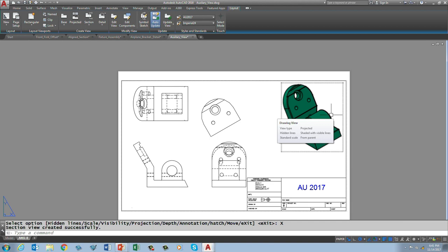Look at the drawing. What's wrong? There's something missing. What's missing? The label is missing. No, the label's missing. What else is missing? Something else is missing. The cutting plane line. Did you say cutting plane line? Very good. You said it. There you go. The cutting plane line is missing. All right, get a candy bar. Yeah, the cutting plane line is missing. True size and true shape is there. Now I could dimension that, true size and true shape, to get that object there.